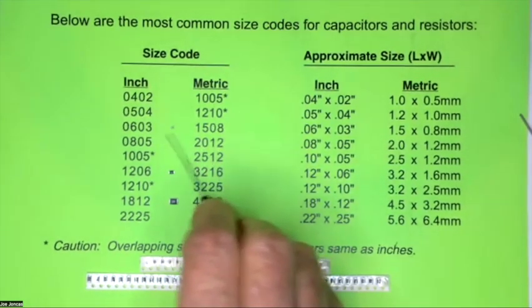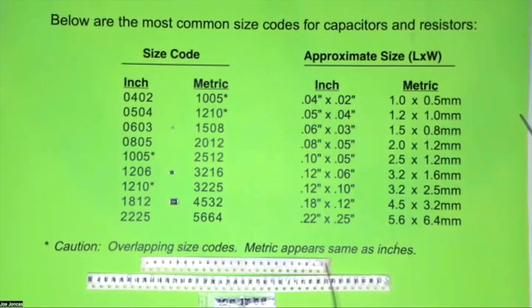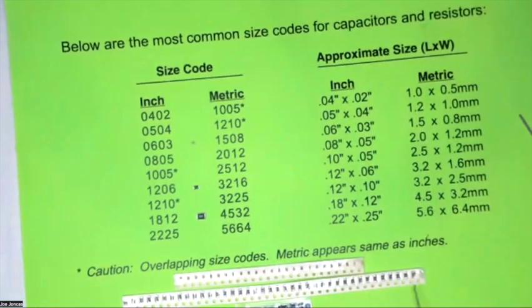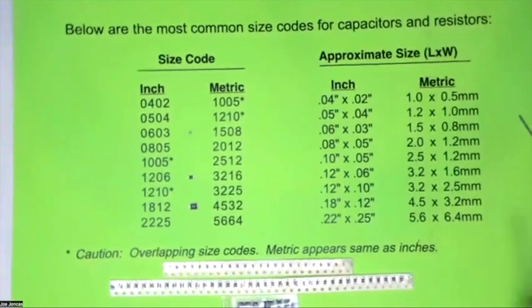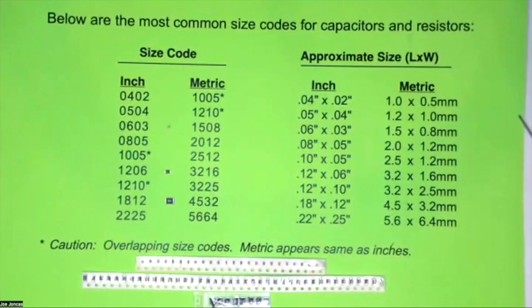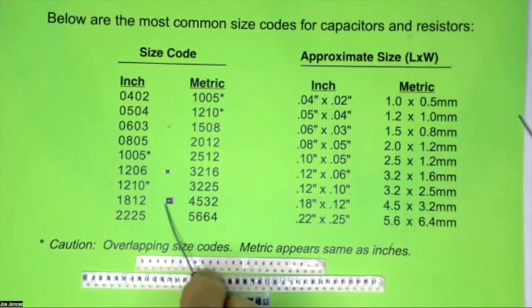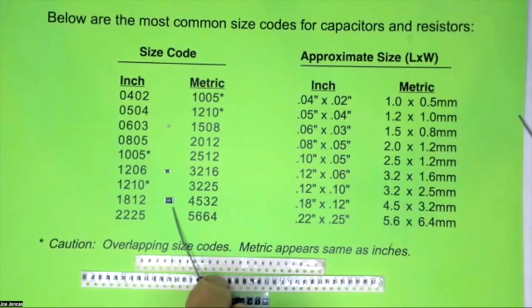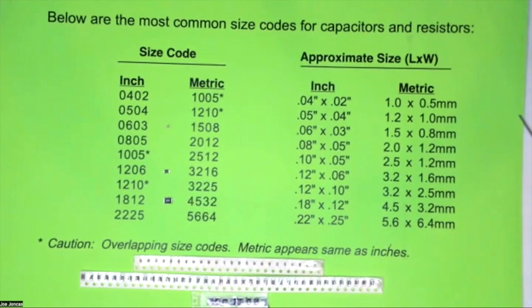This one up here came out of this package, and this one here came out of this package here. They have machines that automatically peel these things open and take them out. And then this one here was another one I needed to handle that power, so I had to get a bigger surface mount resistor and solder it in. But it's that size there.